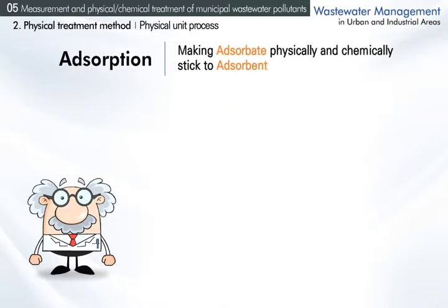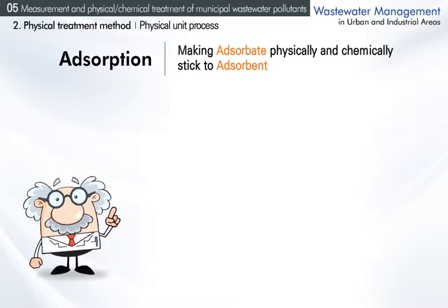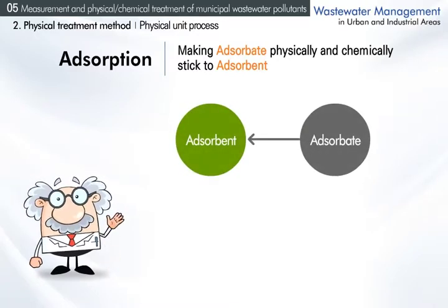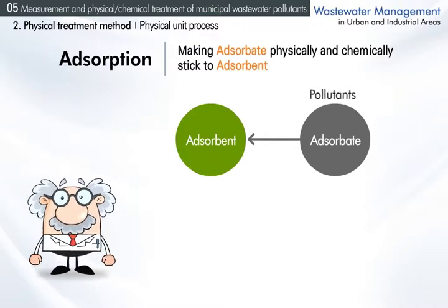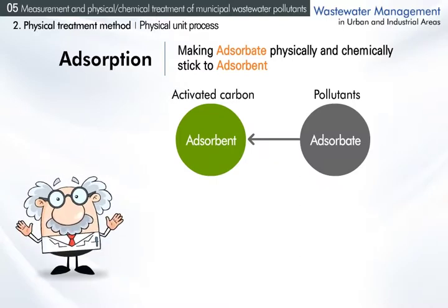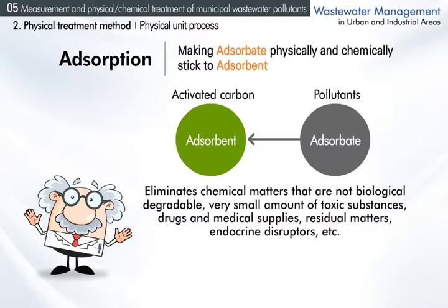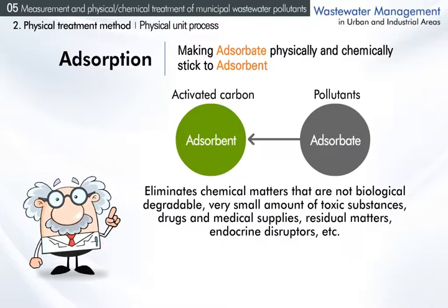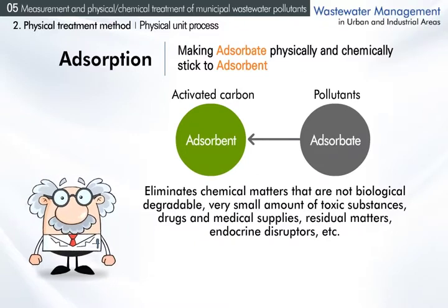Ninth, making adsorbent stick to adsorbate physically and chemically during water purification or wastewater disposal process is called adsorption. Among wastewater pollutants are adsorbates, and matters such as activated carbon are typical adsorbents. Adsorption is often used to eliminate chemical matters that are not biologically degradable, very small amount of toxic substances, drugs